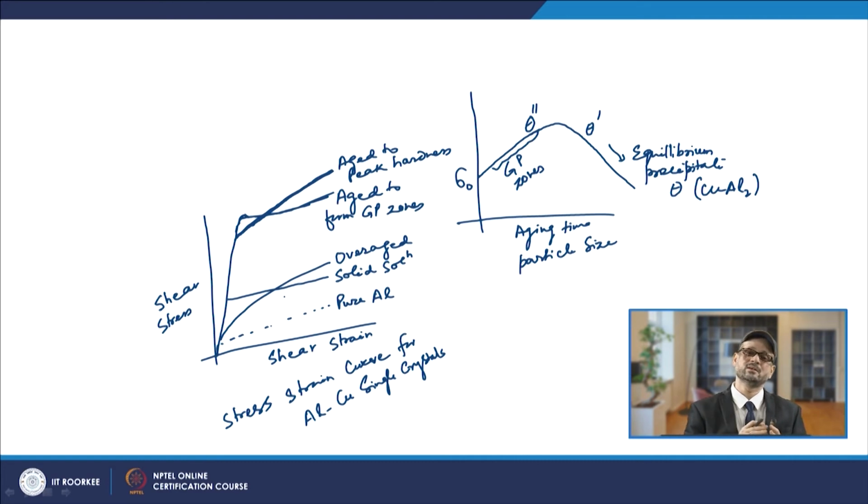Continuously the hardness goes on increasing, and you see a good increase in the rate of strain hardening. So, that tells how with different aging times, different types of strengthening can be achieved, and that is what is suggested from this graph.